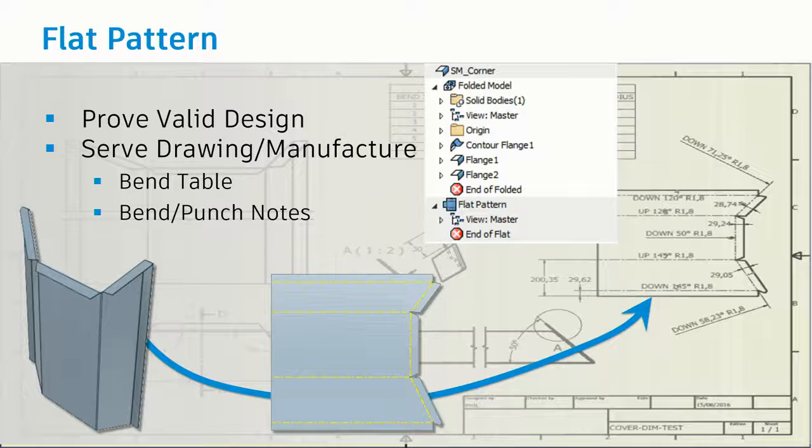The only exception is the iFeature. It's a punch that accepts cut-through features, while other punch features cannot be flat patterned. But it doesn't matter. It just has different representation options for you to choose: you can display the sketch point, the center point, or the sketch, or just this unflat patterned form in the flat pattern status.